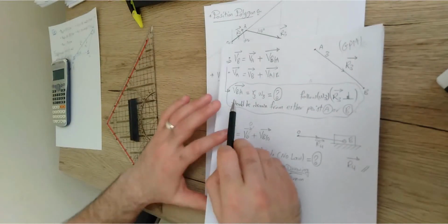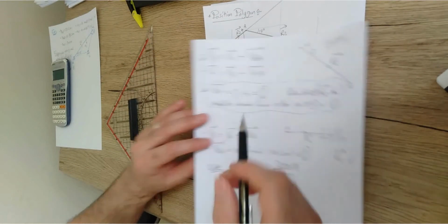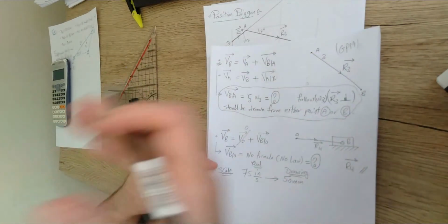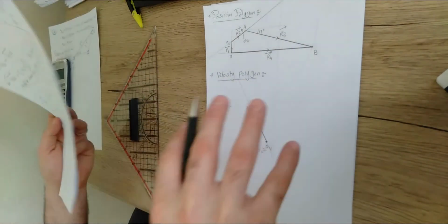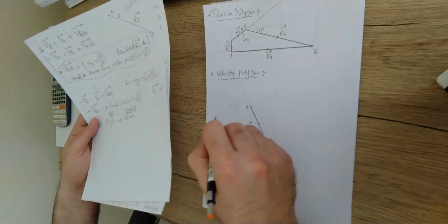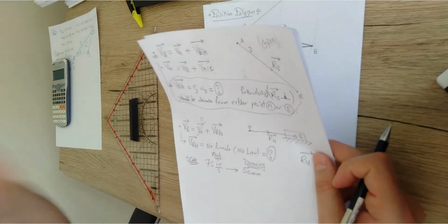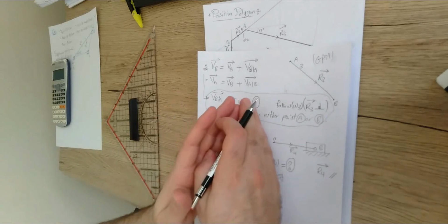This one, again, should be represented or drawn between two points, point A and point B. So it should be drawn in the velocity diagram from either point A or point B, depending on which point is already located or defined in the velocity diagram. Here, we already located point A. So from point A, I'm going to draw point B. Very simple. Make sense? What is the magnitude? We have no clue. It is unknown.